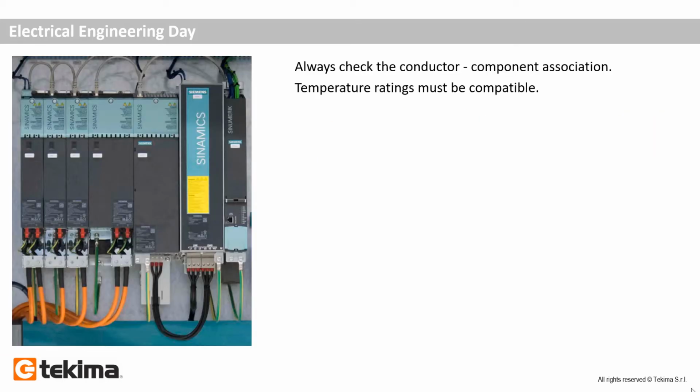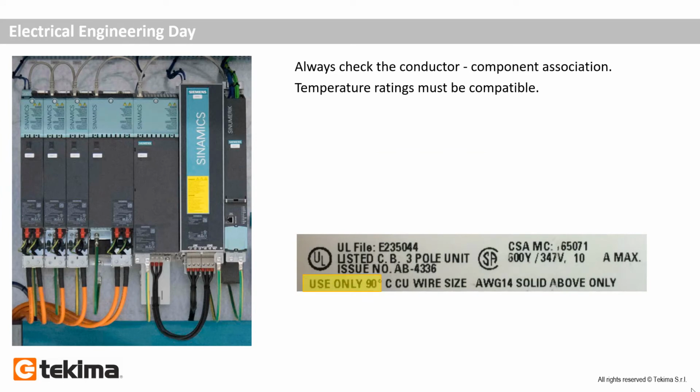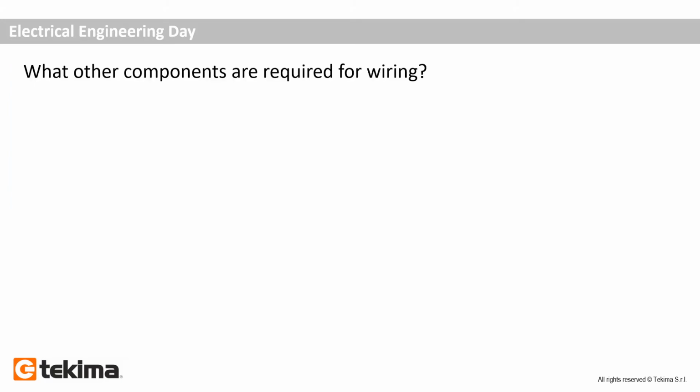One important thing is to double check the temperature rating of the cable and the temperature rating of the associated component. What other components are required for wiring? We spoke about raceway or cable tray. Each one of these components is defined in the standard, and you can find all the references on it.